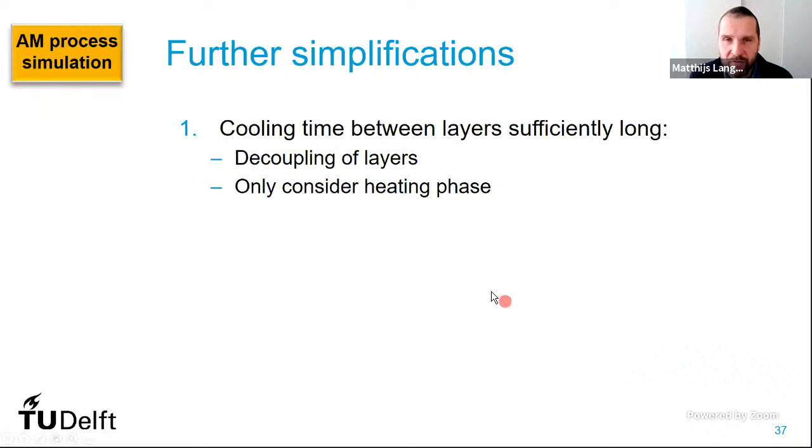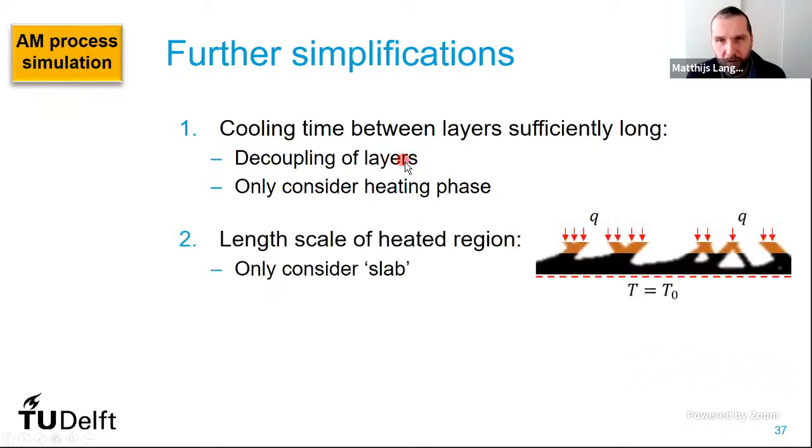So there we observe that between depositing layers, there's usually some cooling time because a recoater comes by, new powder is deposited, and so on. If this cooling time is sufficiently long to drop back to a kind of base temperature, you can decouple all the layer thermal simulations and do them in parallel. Also, it allows us to drop the cooling simulation and only look at the heating phase.